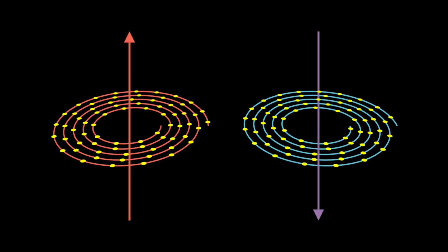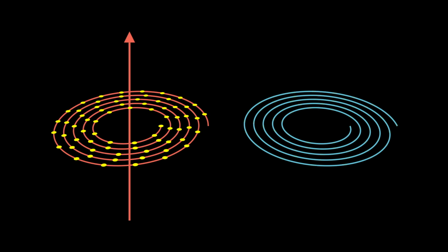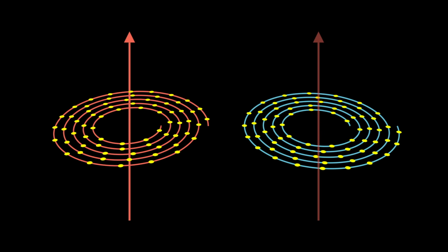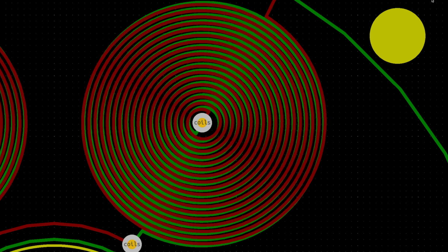If we look at the direction of the magnetic field that will be created from the two coils, we can see that they will cancel each other out. To fix this, we just need to flip the bottom coil. The current will now flow into the top coil and out of the bottom coil in the same direction. The top and bottom coils will now reinforce each other. Generating this and turning it into tracks and vias results in this very nice looking PCB layout in KiCad.